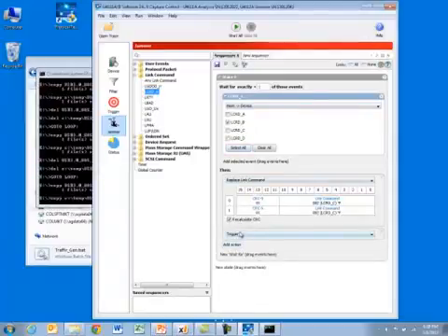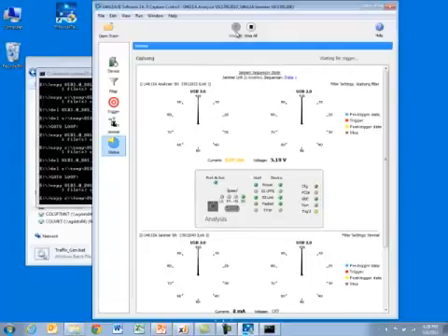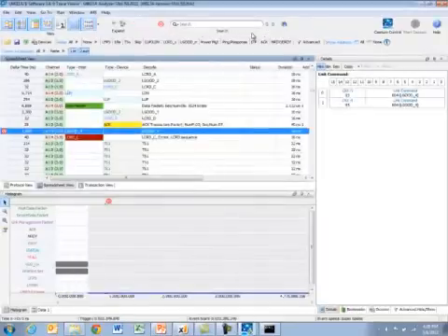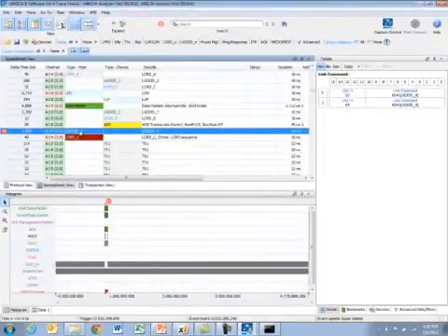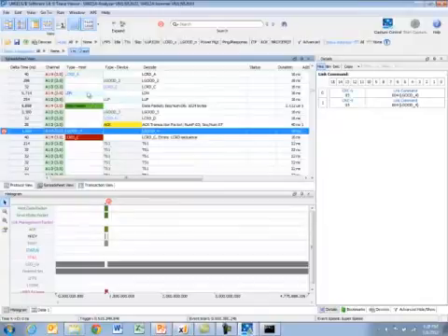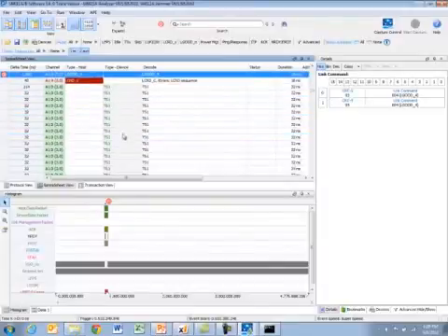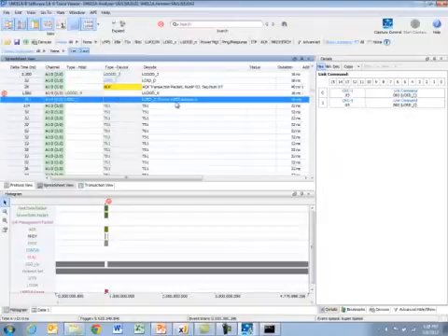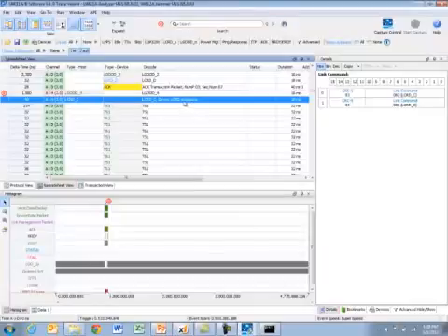When it does that, let's add the trigger condition. And let's not do it on the first one again. Let's do it on the 100th of that. Run the little command, run the script, it triggered. I can look at the sequence. Link good occurred. Link credits were flowing back and forth, A, and it went to C. The device immediately went into recovery mode to bring the link back up. So we can see that it's highlighted the CRC sequence error, or the CRCs were good, but the sequence for the link credits was corrupt.